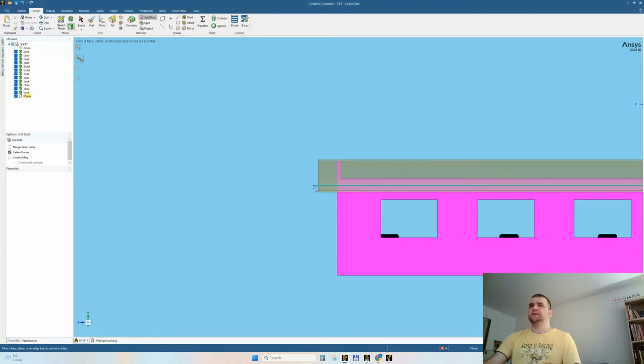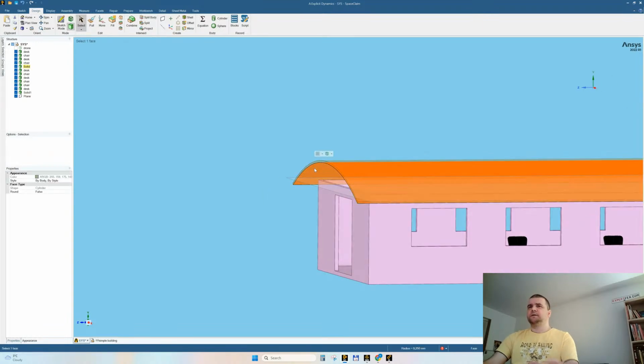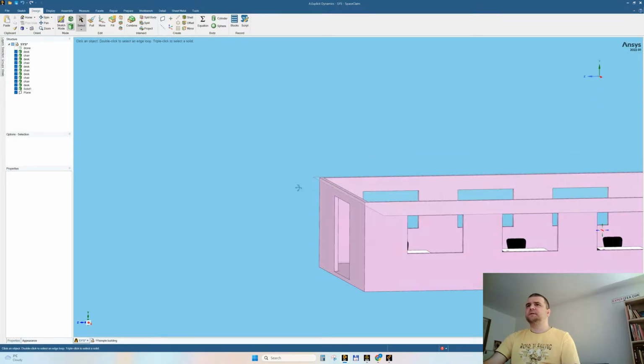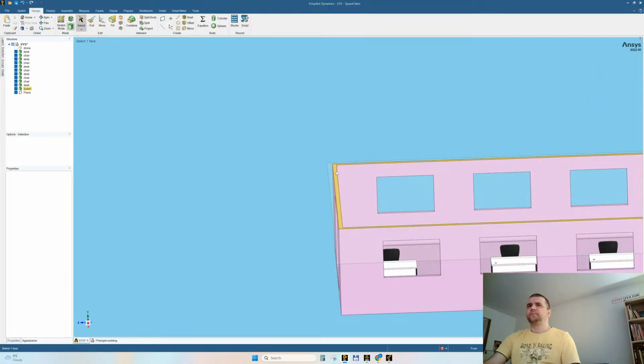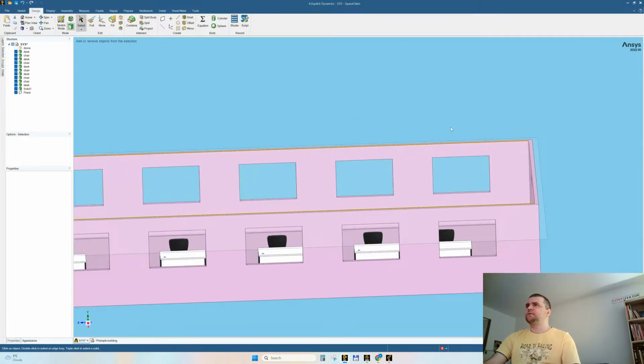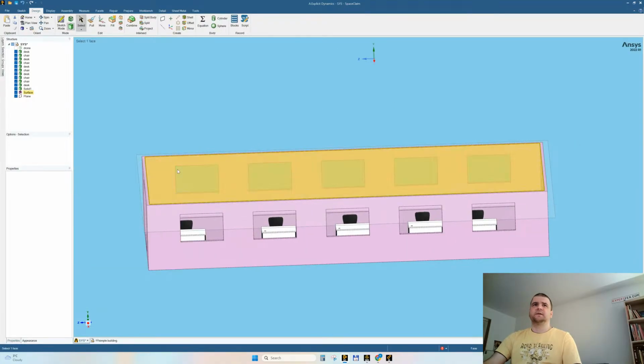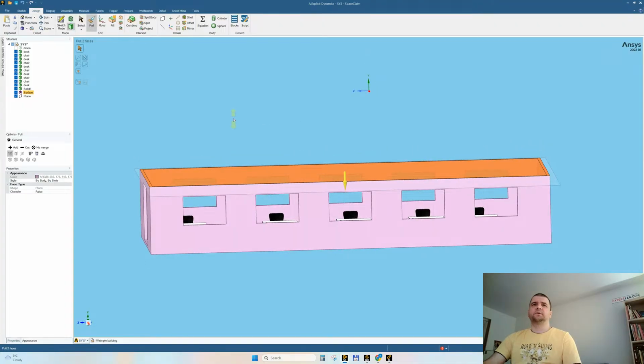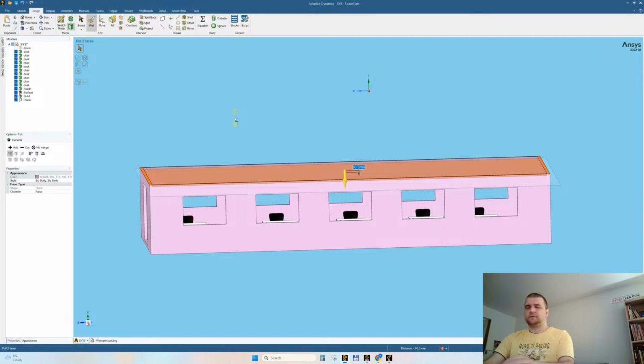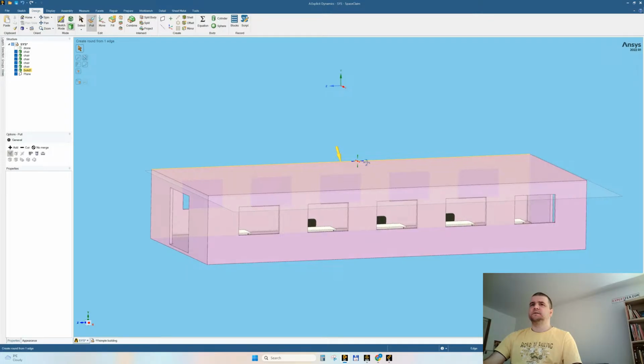This one with this plane, and I will remove this thing. This I don't need at this time. Let's click these four sides and click here, fill. Once I click fill, we have two surfaces. And I will pull up. How much should I pull? 70. All right, so this is the office building.